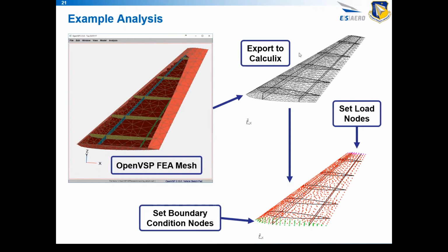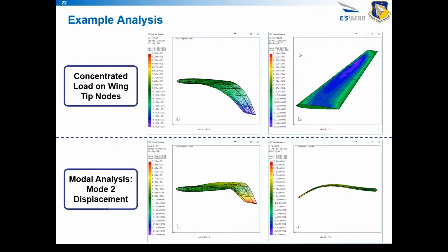The primary purpose of this was not really to assess the results of the analysis, mostly to just check, when we apply a boundary and load condition, does the mesh stay together as we expect it to? Do we have that correct connectivity there? If you could see here with these exaggerated deflections and displacements, we do keep everything together. I wouldn't focus too much on the values of the results that you're looking at. This was just done to prove, yes, we have the connectivity that we expect. And so you should be able to use this tool for a more detailed analysis if you'd like.